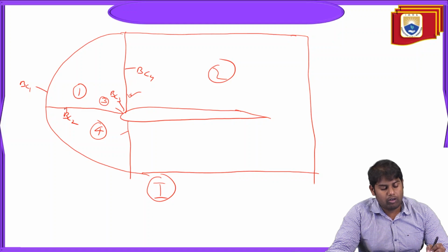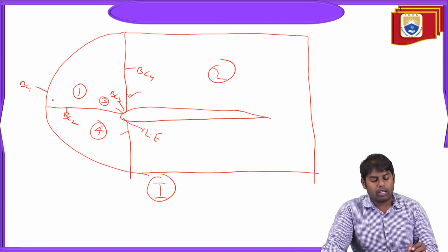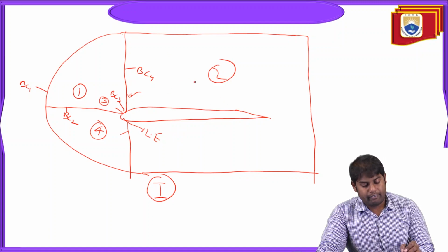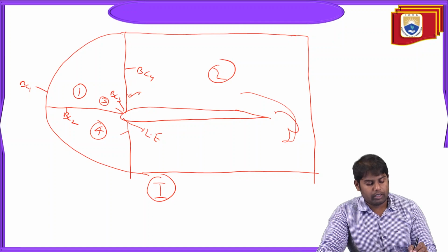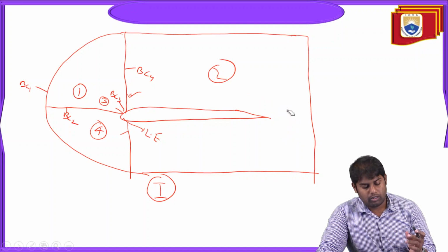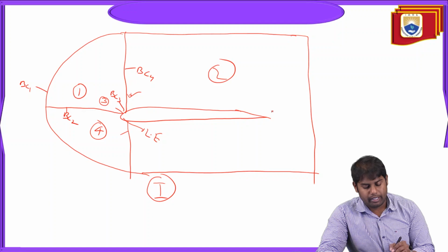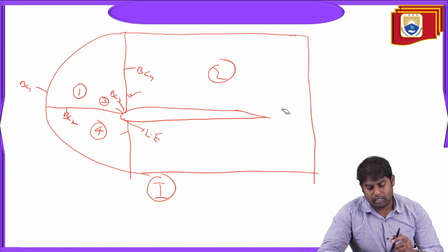When we draw like this, on the upper surface and on the bottom surface, at the leading edge of the airfoil, we are able to generate a C mesh. Now here, there is nothing, we don't have a closed setup, it's like an open one. Here you can see it's empty. Whatever grid points we have here have to match this one, but somewhere in this region it will form a negative volume. Why? Because there is no entity forming a closed setup.